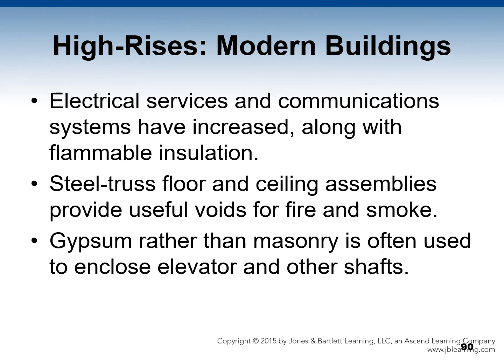Electrical service and communication systems requirements have increased, along with the insulations that are combustible. Steel truss floor and ceiling assemblies provide useful voids for fire and smoke. By dropping ceilings, useful voids are created and then connected via utility shafts. Gypsum rather than masonry is often used to enclose elevator and other shafts. Stairways are often located in the core without fireproofing.